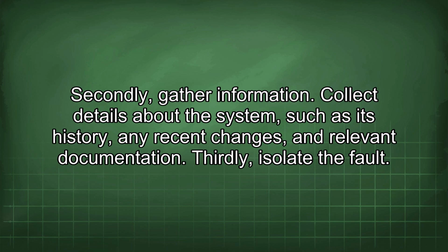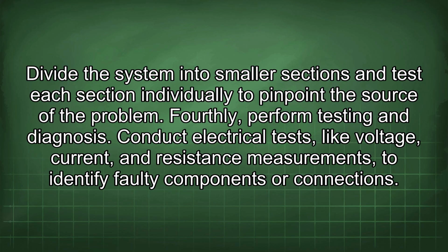Thirdly, isolate the fault. Divide the system into smaller sections and test each section individually to pinpoint the source of the problem. Fourthly, perform testing and diagnosis. Conduct electrical tests like voltage, current, and resistance measurements to identify faulty components or connections.